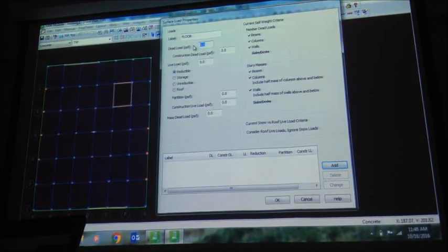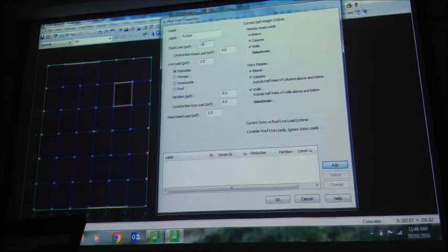Now remember I said that I do not want my slab to be calculated by itself, by the program. I want to give the load, right? So a 10-inch slab is 125 PSF, if you remember. 10 by 12 multiplied by 150, that's 125. Plus another 25 PSF for a kind of finishing, marble or whatever you want. So another 25 makes it 150 PSF dead load.